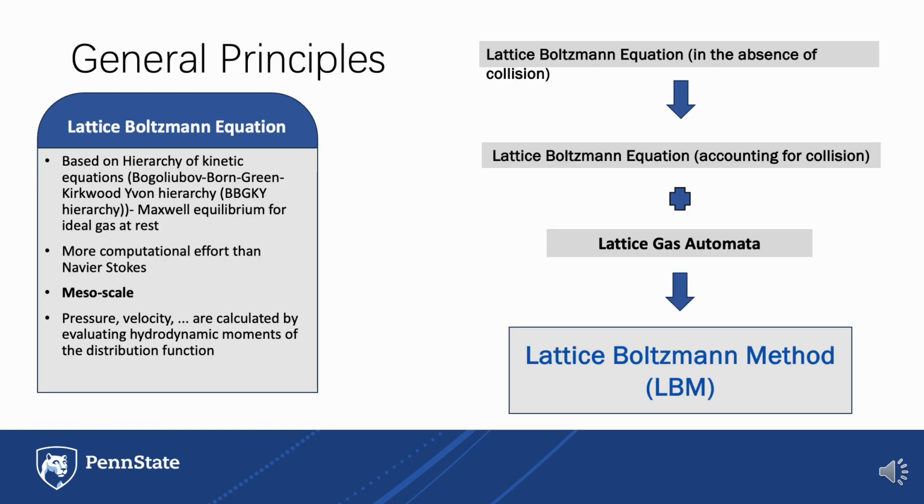However, the early forms of the Lattice-Boltzmann equation accounted for only gas at rest, or equilibrium. Therefore, it was further developed to account for non-equilibrium conditions. And to accomplish this step, a concept called distribution of particles in phase space needed to be utilized, which in essence is the probability of a particle to be at a certain position and velocity at a certain time.